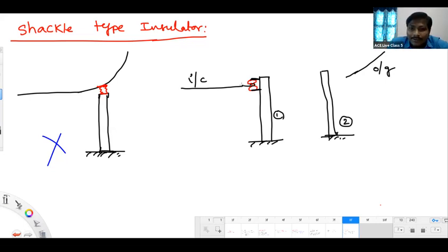So that your incoming wire will be mechanically stable. So this red color insulator we are keeping here, red color dumbbell shaped insulator. Similar insulator we keep on the other side also like this. It's also a dumbbell, and top and bottom of this insulator will be again connected to pole, and this conductor will twist onto this in that manner.